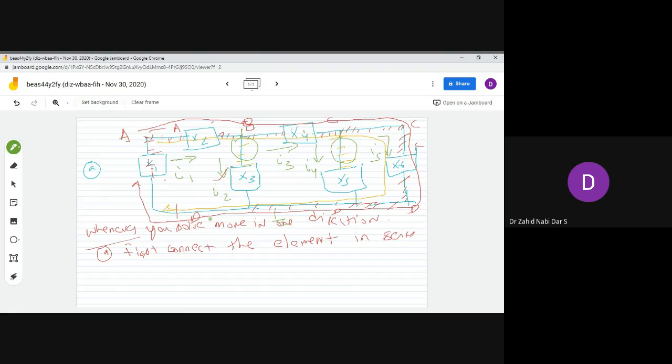So now when you will be solving the nodal analysis technique, this is the prerequisite what is required for solving. Where the people are making a lot of mistakes is in the sign convention they take. So remember, passive sign convention you have to take. That means plus and minus like this. If it is, then only you have to take this. You cannot take the active sign convention. Okay, this sign convention you have to remember when you are solving the circuit.